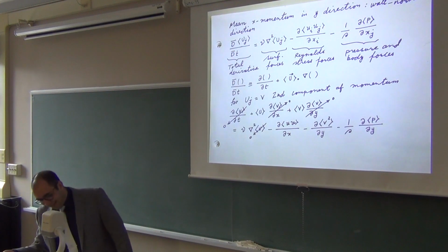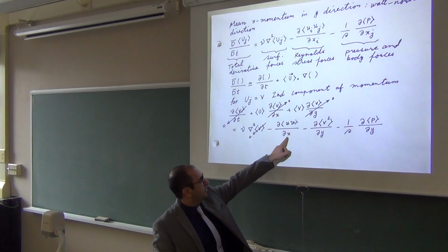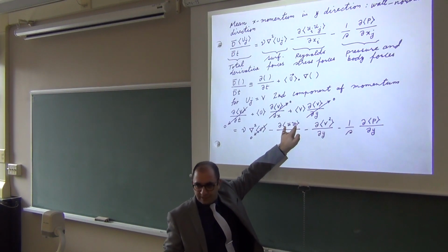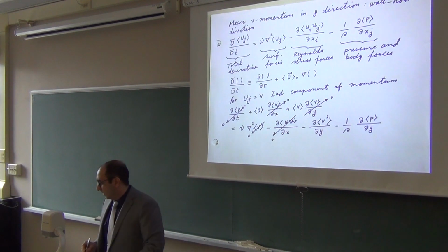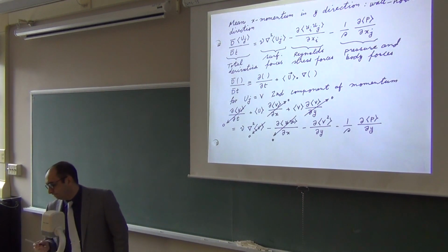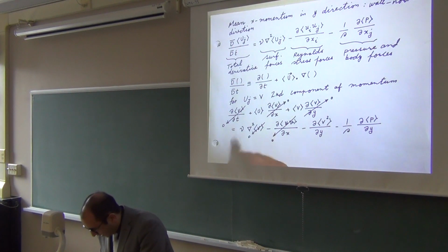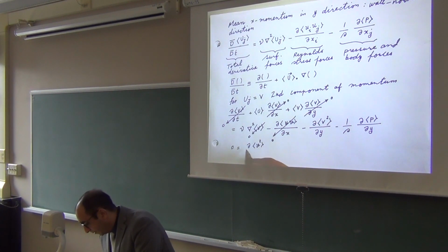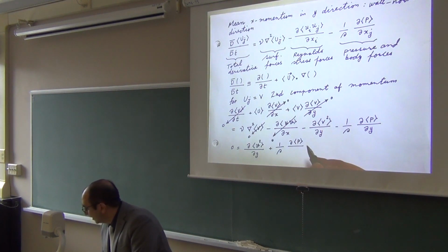And again, this term shows variation with respect to x, or along the direction of the flow. For fully developed flow, none of the statistics change with the flow direction, and this is a statistic, uv. It's not going to vary for a fully developed flow. I'm only left with the last two terms there, which is this. I could knock out the negative sign, so here I'm left with partial of variance of v, partial y, plus 1 over rho, or density, partial pressure, partial y.